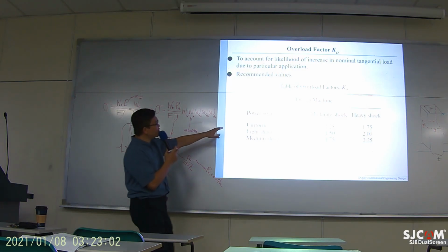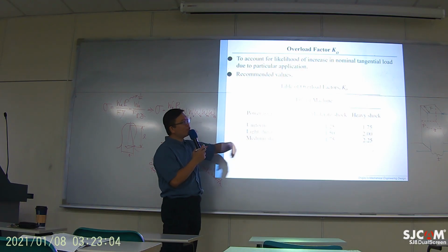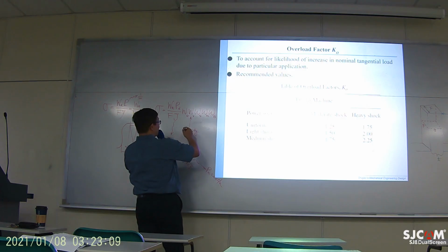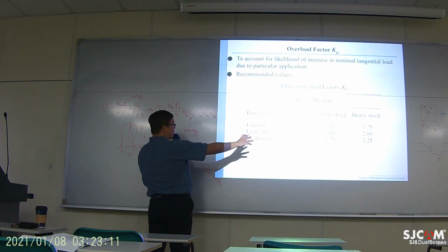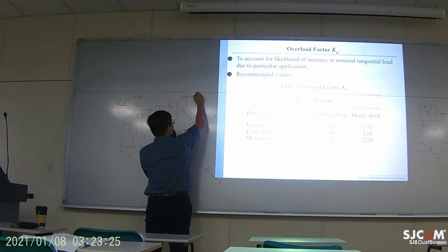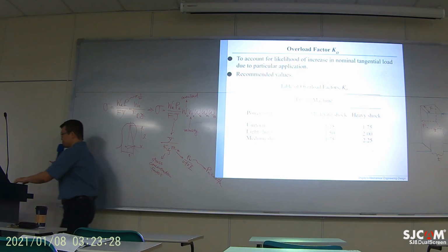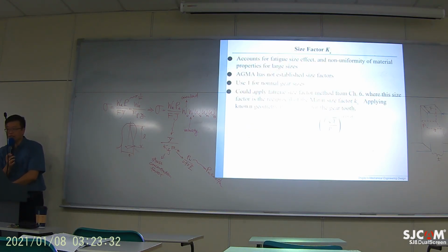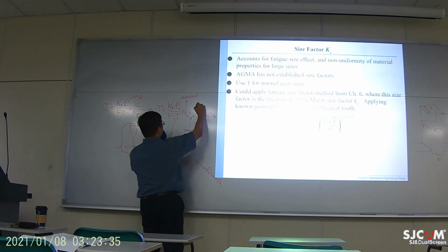So if it's a uniform loading condition, then you just apply one. But if you have a heavier shock condition, then you may need to multiply the stress. So this is about the overload factor. And then Ks is about size. So this is about size.